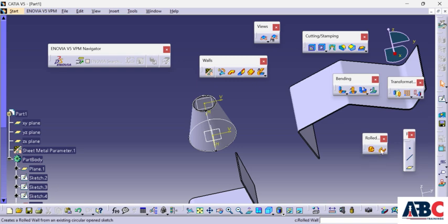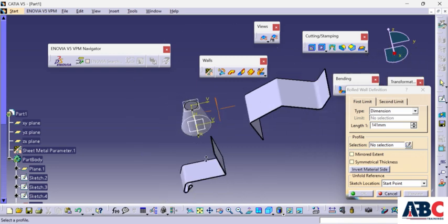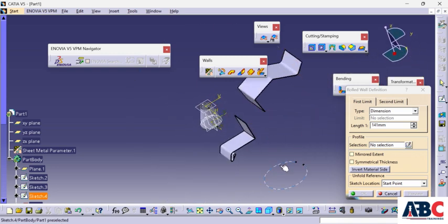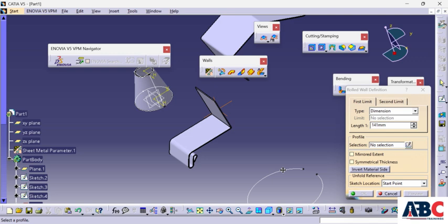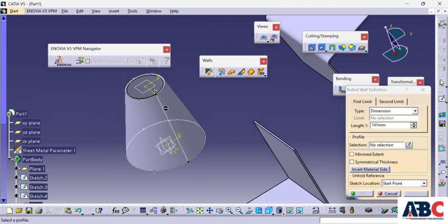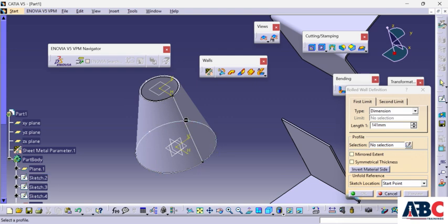So we will see the next one, which is the roll wall. Okay, so for the roll wall I have created another sketch. So this is the sketch. So you have to create this type of sketch for the roll wall. For the hopper you have to create a sketch circle, then the next sketch on the offset plane of that circle. Okay, and then there is this second point, and a line joining both the points. So this is a spline, this is first section, second section.